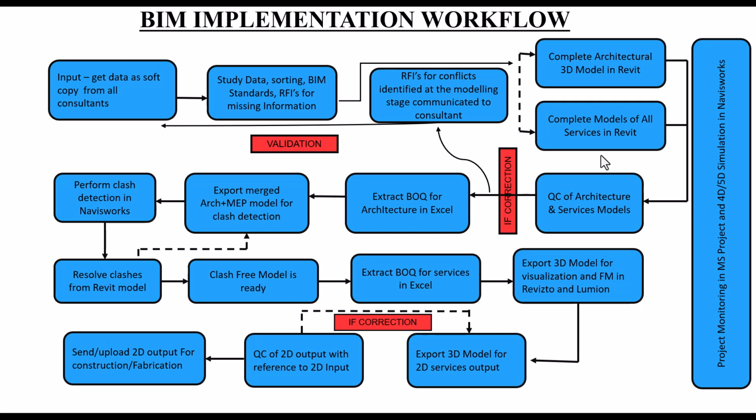So you are going to monitor it, you are going to create a 4D 5D simulation, you are going to detect the clashes, you are going to make a clash-free model, you are going to extract the BOQ for the entire materials and the quantities inside the project, and ultimately you are getting the drawings at the end of it. So this entire workflow is called a BIM implementation workflow, which is basically CAD to BIM.